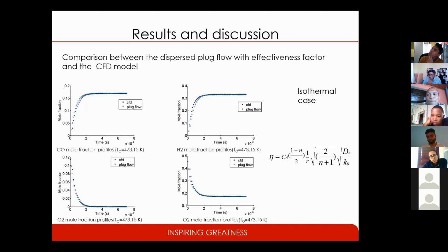So what you've said there is true, but I don't think it's the answer. I think if you think of it, think of this monolith as a catalytic converter, right? And someone's going to buy a catalytic converter and install it in their car, and now everything is completely combusting in that 5 millimeter gap at the start, but also the catalyst deactivates over time and it cokes and all that.